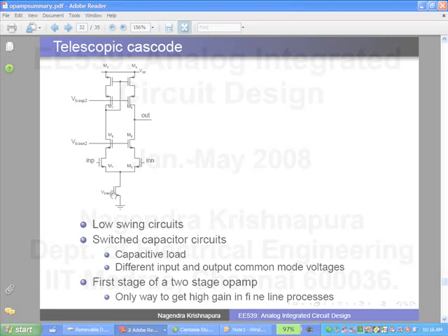Yeah, the question is whether scaling width is better than scaling length and width. I mean, we are talking about two different things, right? First of all, this current being proportional to W by L is valid only in strong inversion saturation for long channel transistors. Okay. When it goes into velocity saturation or anything of the sort, that is not valid at all. So in that case, scaling with L is just out of the question. The only thing L does is, if you use a longer channel device, you will have a larger parasitic capacitance.